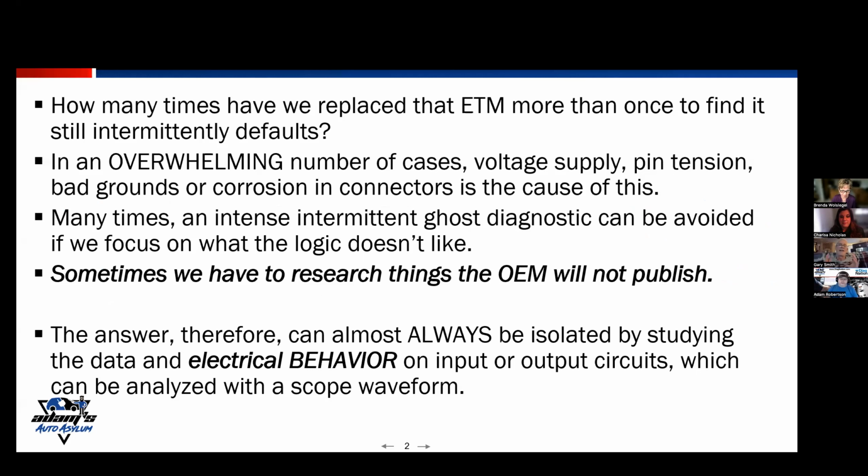How many times have we replaced something like an electronic throttle motor or a Valvetronic motor or something of that nature, or even a driver or a control module, only to find that the vehicle still has its intermittent fault that we were going after? Well, what we're finding, and we're going to dig into a chipset here today to show you why this is important diagnostic information, is that in an overwhelming number of cases, we've got certain things going on that are creating, let's say, that Valvetronic motor to reset, or say the throttle motor in this case to reset.